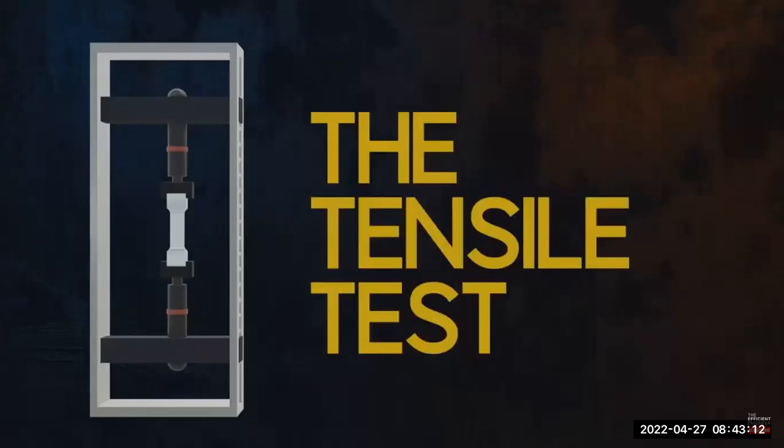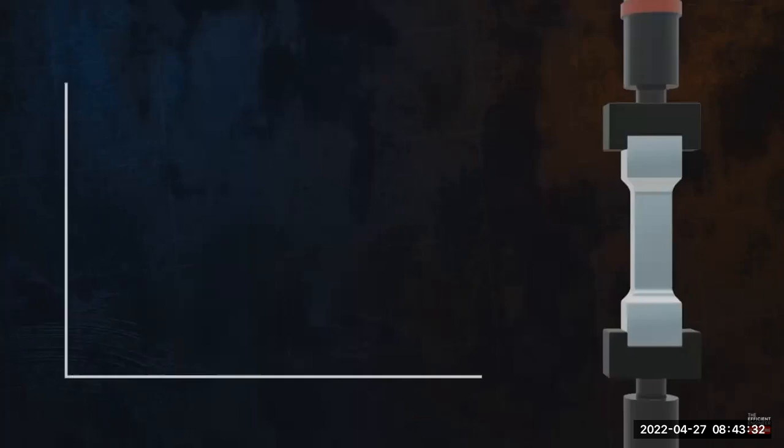Let's introduce Young's modulus using the tensile test. The tensile test is a very common mechanical test, which takes a test piece and stretches it along its length. It is a uniaxial test, meaning that it applies a load in one direction only, as shown here. During the test, the machine measures the applied load and the change in length of the test piece. The main output from the tensile test is the stress-strain curve, which describes how much the material we're testing will deform for different levels of applied stress.